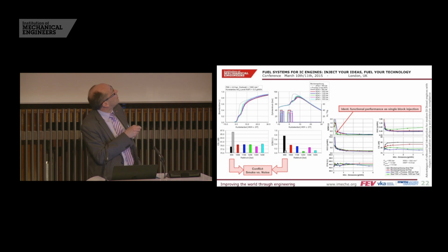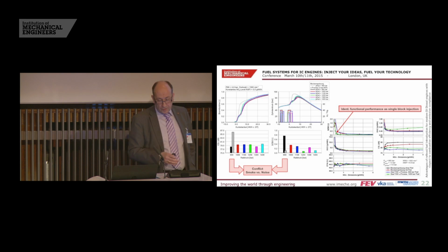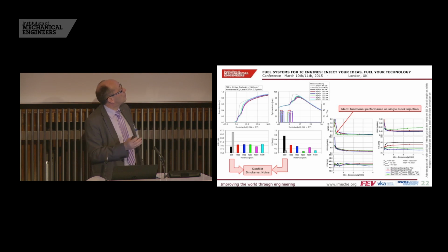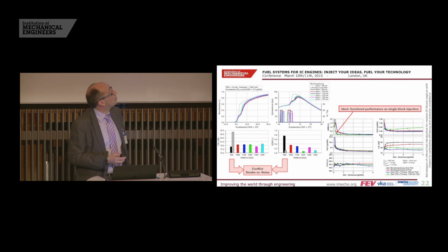And you see this here by these different curves plotted in gray or in black, how the combustion trace and the burning function looks like. And then the big thing is how to manage a kind of digital rate shaping here by actuation of the injectors, depending on the capabilities of the hardware in terms of hydraulic, but also electrical capabilities, but also the corresponding software algorithms which are available to control these functions.